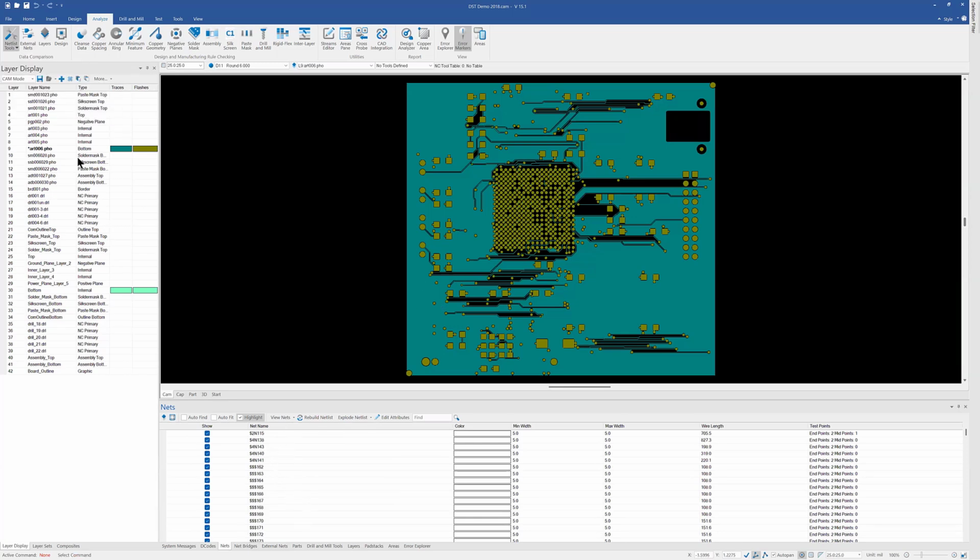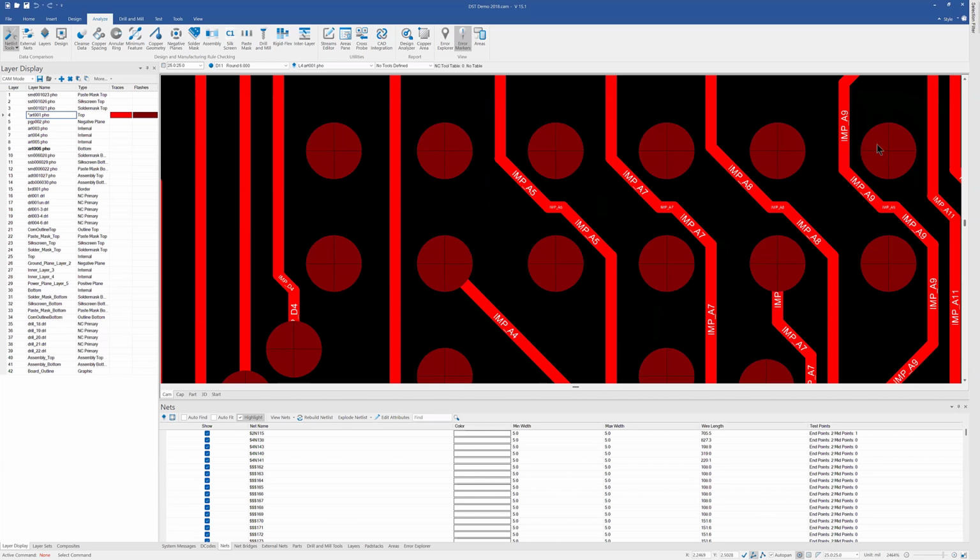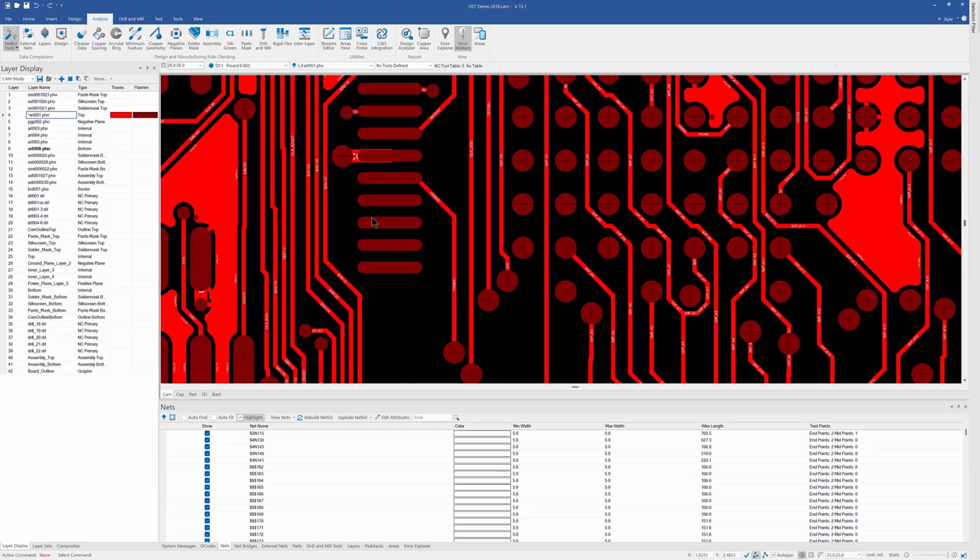And so now you see the intelligent net names there. When you're working with the data, I don't know if you're aware of this, but we actually superimpose the net names on the tracks. So you'll have the new intelligent net names, impedance A5, impedance A7, and so forth, as opposed to just numbers, which is what happens when you just do the Gerber extract.